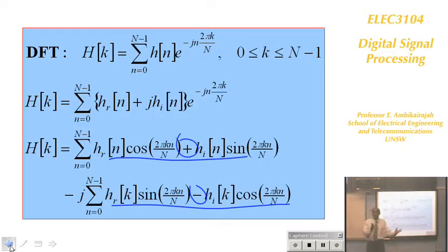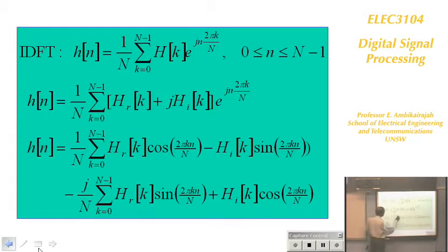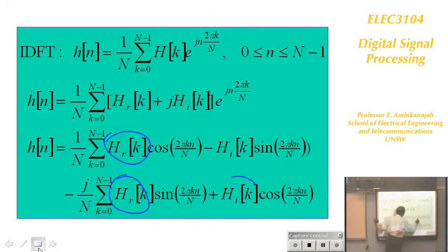So FFT, DFT and inverse DFT can be implemented with the same formula, except in this is for DFT, and for inverse DFT, this will be frequency response. That's the change. Sign is changed. So really, if you devise an algorithm for DFT, you can implement inverse DFT using that algorithm.